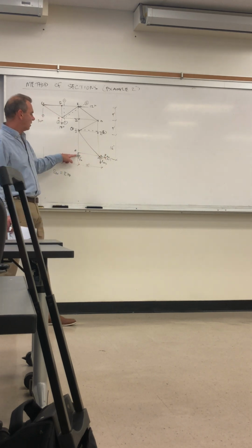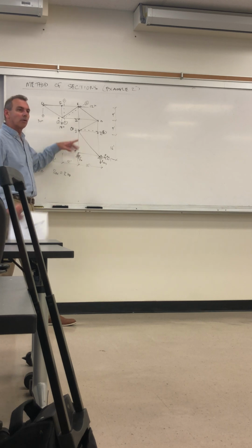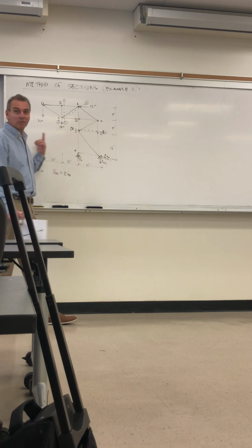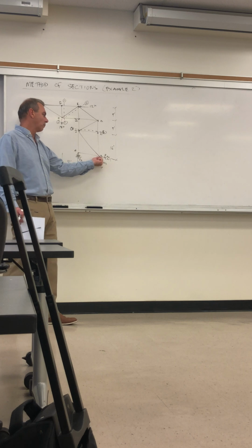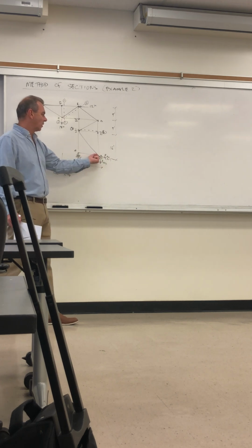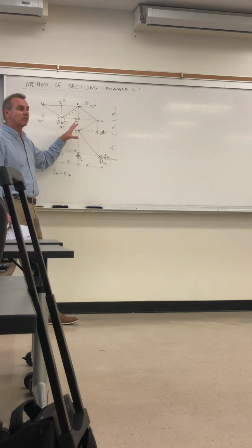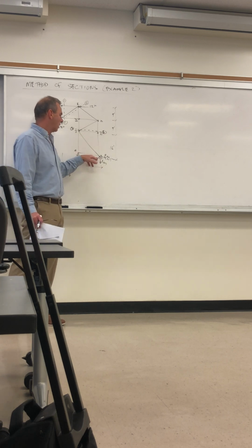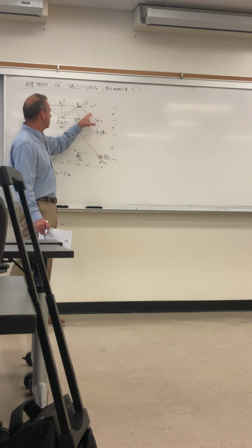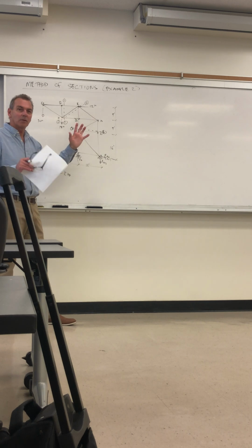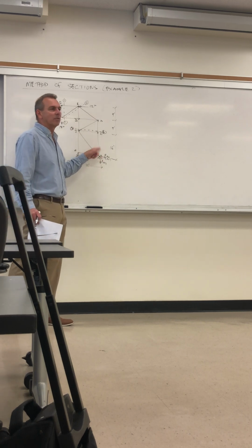And vertically also, same with this one. Horizontally, this might move an inch or so as the structure strains, stresses, and deforms. It's not going to go 1,000 feet, which is what we're preventing by providing the pin. Even if you put this in a computer program, you'll get small displacements throughout the structure as it reaches equilibrium, but that location will say 0, 0.